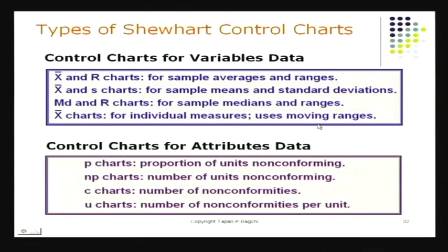Now that you have understood what control charts are, you've looked at an XBAR chart and an R chart. I'm going to be showing you some more of those. The other charts are all very similar. The spirit is the same. Try to distinguish between exceptional variation and natural variation. The moment there is exceptional variation, this is when you'd like to take some action. And leave the process alone if the variations are natural. Because every teller knows that there will be some variation signature to signature.